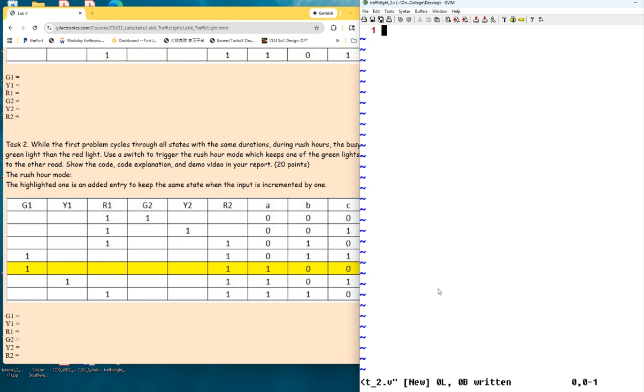If you just simply use different states, okay? And once it reaches one specific state, you just use a different count max. You have 2 different counters that just counted. Oh, actually it's 1 counter, but it counts to a different count max. Then the problem is solved. And you can just describe everything within the behavioral modeling method framework instead of thinking about the logic circuits.